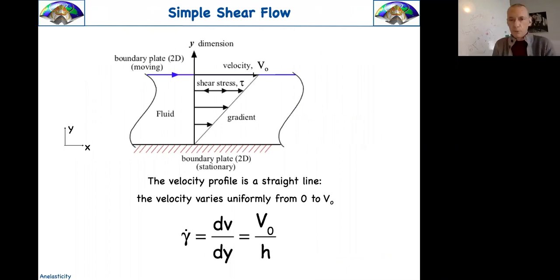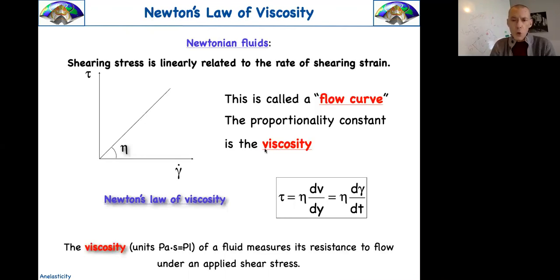So the typical example of this is shear flow in a fluid that is not an ideal fluid. An ideal fluid will not move. You're not going to generate anything there. But in what we're going to call a Newtonian fluid, the profile that we're going to generate is a line whose slope is decided by one additional property that is called viscosity. So the slope is constant and you have the maximum velocity here that corresponds to the velocity with which you are pulling the first plate, going to zero here because that's a boundary plate and it's fixed, you cannot move it. If you generate a profile like that, the fluid is called a Newtonian fluid. And the slope is decided by this, and this is called viscosity.